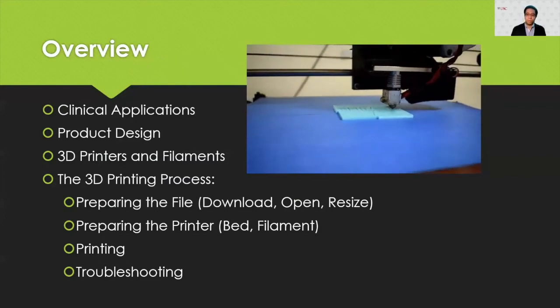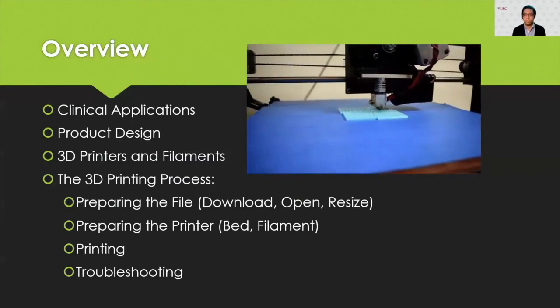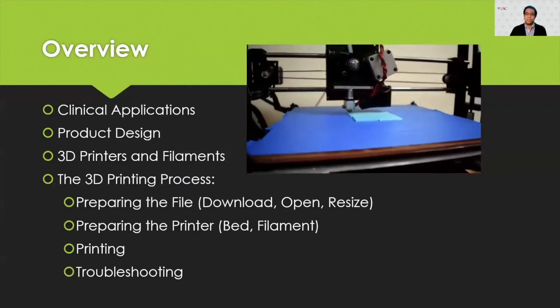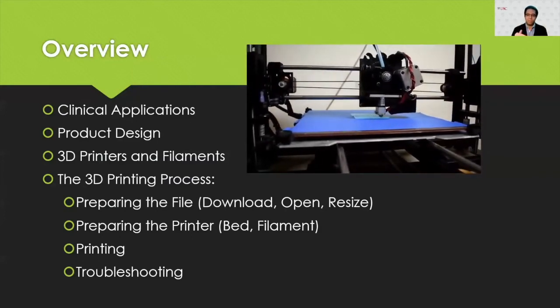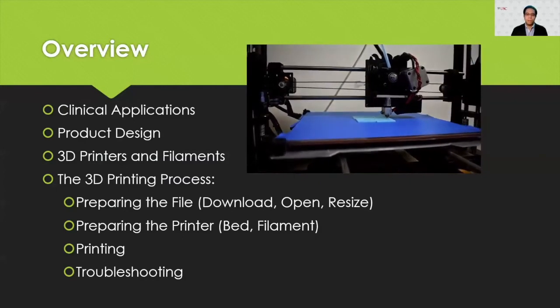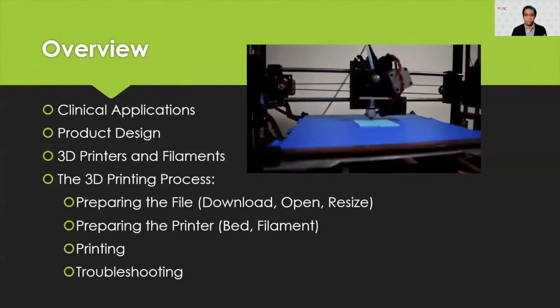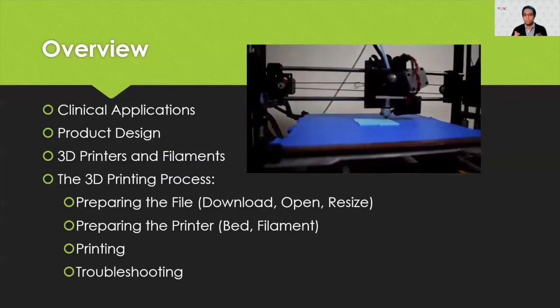As Dr. Liu explained, this manufacturing process essentially consists of creating three-dimensional objects by consecutively adding two-dimensional layers of material. For this presentation, we will focus on a process in which we melt plastic in specific coordinates to create the layers of the object. However, please keep in mind that there are other processes available that allow for different costs, precision, manufacturing times, and materials.